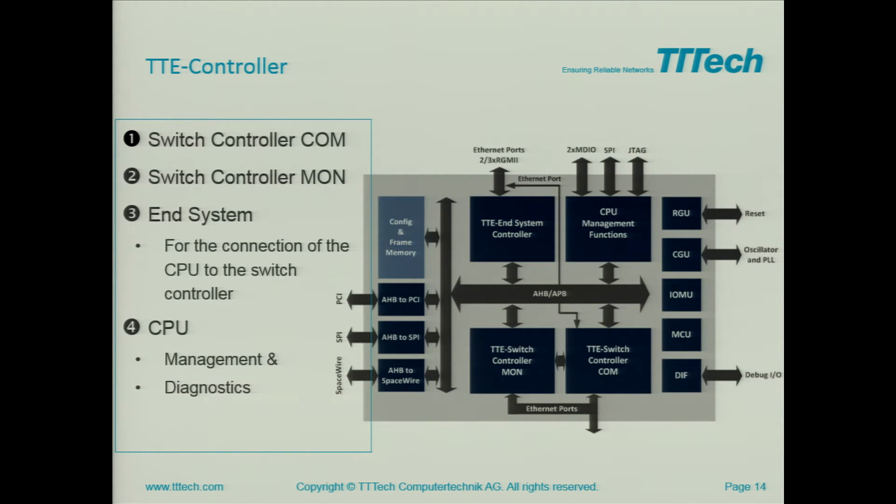When we now look a little bit into the different blocks, the CPU is there for TFTP and SNMP. TFTP is for configuration loading onto the switch, to define the routes of the messages. And SNMP is there for standard diagnostics. I think you know that from standard Cisco switches, for example. There you also have TFTP and SNMP protocols.